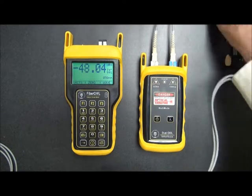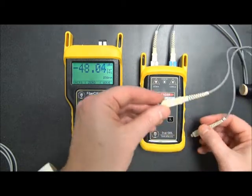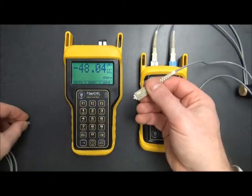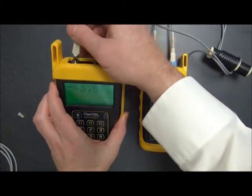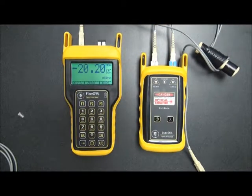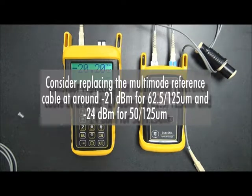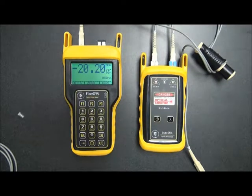And then let's measure the 850 nanometer first. So we find the 850 nanometer cable and we plug it back into the detector port here. Now, as you can see, it's reading around minus 20.2. Remember, we want to be around minus 20 as far as reference level. Now, this is acceptable. Typically, when you reach around minus 21 or so is when you really want to start looking at replacing your cable. But for our purpose here, minus 20.2 is very good.